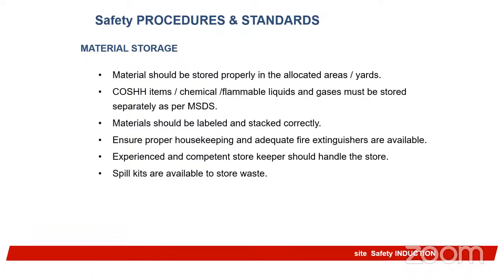Materials should be stored properly in the allocated areas. Areas that have been created to store petrol should be for petrol. Areas that have been created to store nitrogen should be for nitrogen. Areas that have been created to store fire extinguishers should be for fire extinguishers. So flammable chemicals, liquid, and gases must be stored separately as per the SDS. SDS is safety data sheet, material safety data sheet.